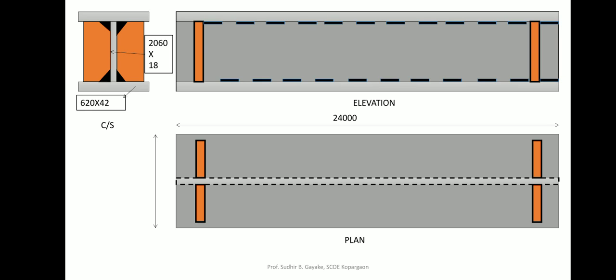Only remember, in case of girders, the welding is to be provided as intermittent welding, because continuous welding throughout is not possible for the given span of 24,000 mm or 24 meters. So likewise the numerical will be completed.